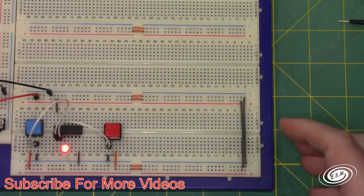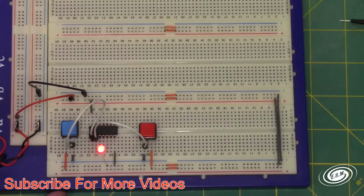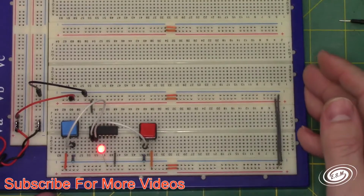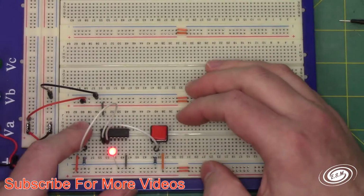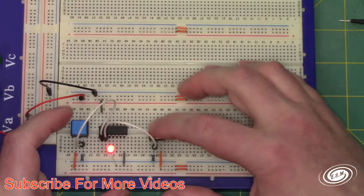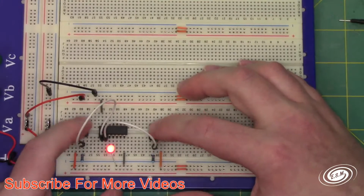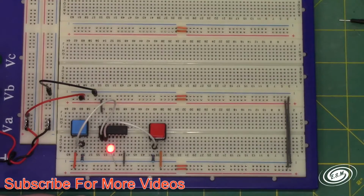They tend to run at a lower amperage than your TTL chips, which would be the 74LS series that we'll be looking at later. But back to this circuit: if one's pressed, nothing happens. If the other's pressed, nothing happens. And if both are pressed, it turns off. If both are off, it is on. And that comes back to our truth table over here.